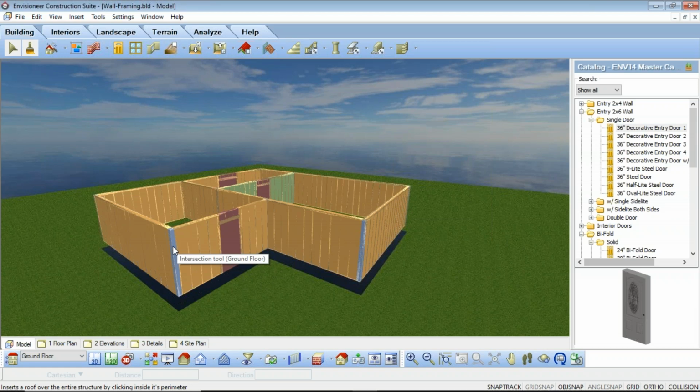So first, let's go in and let's select a wall infill. So let's say that this wall, and this wall is our kitchen. So I want these walls to be blocked. So I want to make some edits to just these three particular walls. Again, to do that, select one wall, hold your Shift key down, and you can select the other two walls. So I now have three walls selected. Two are cyan, one is green.